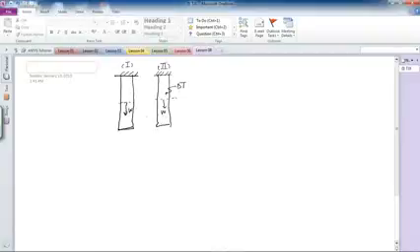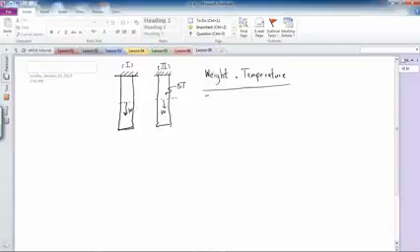So when it comes to analyzing the deformation of a beam based on its own weight and temperature differences, what we have to do in ANSYS is to define two other material properties except for elasticity and Poisson's ratio. Again, I'm going to use steel as the material for this analysis, for which we know that elasticity is 200 gigapascals and Poisson's ratio is almost 0.3.